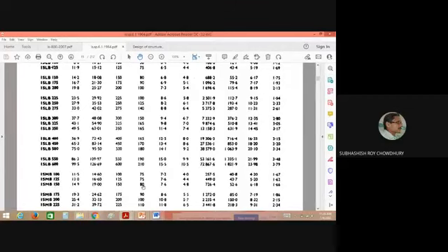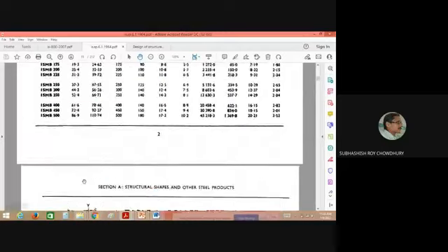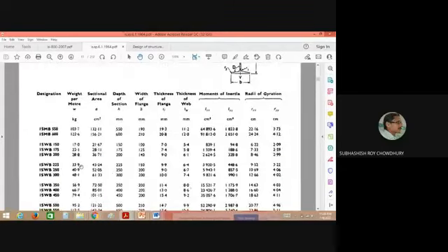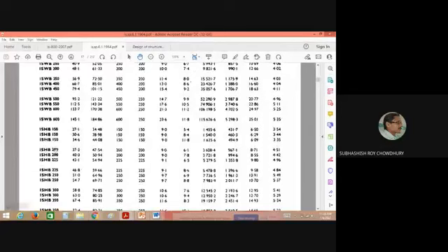So the widths are same, but the thickness of the flange and thickness of the web will vary. It is 6.8, it is 7.6, it is 4.8, it is also 4.8. Some of the cross-sectional properties will vary, mainly the thickness, and according to that it is changing from ISLB section to ISMB section to ISHB sections. You just check ISHB 150.